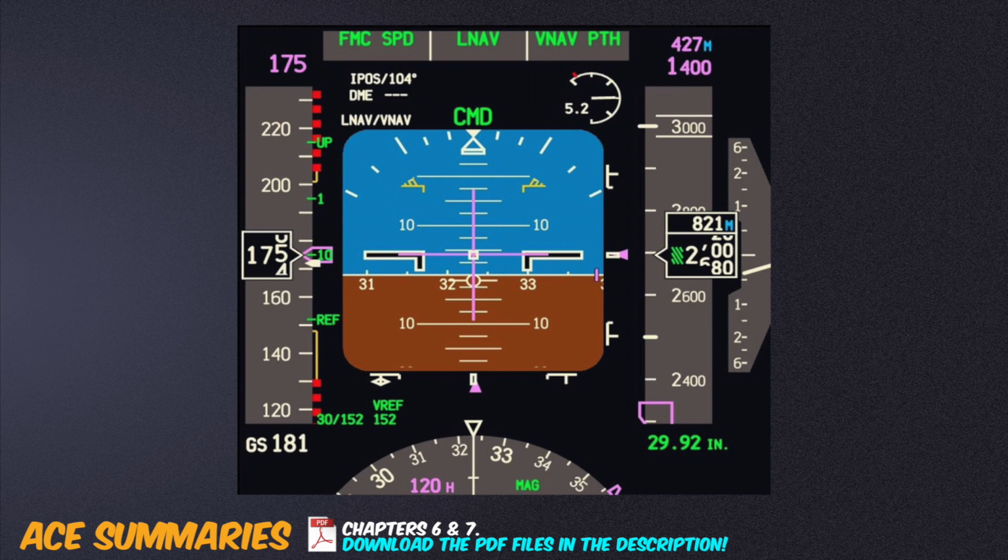The EADI display often includes the following information: attitude information, including the turn and slip, from the inertial system, flight director command bars, pitch limit indicators, as well as a rising runway indicator. The EADI also includes speed tape with trends, as well as a Mach and ground speed display, LNAV and VNAV deviation indicators, altitude and radar altitude indicators with minimums bugs, autopilot modes including auto thrust, pitch mode, roll mode, and autopilot status.